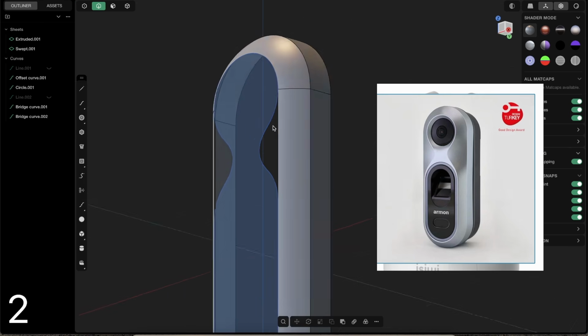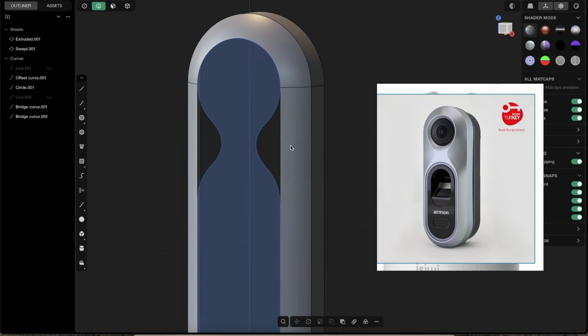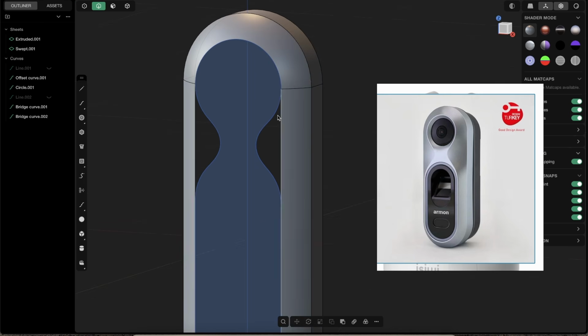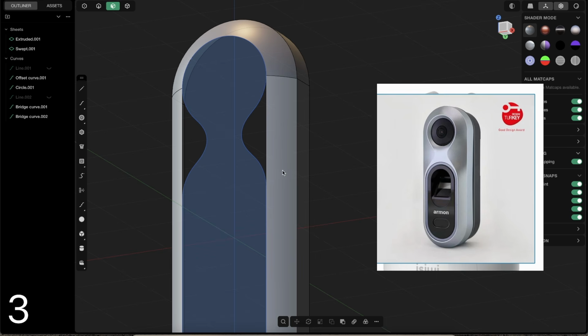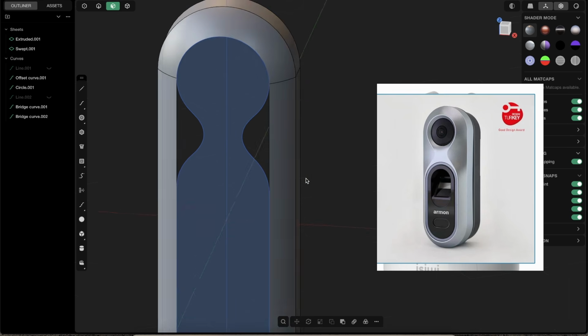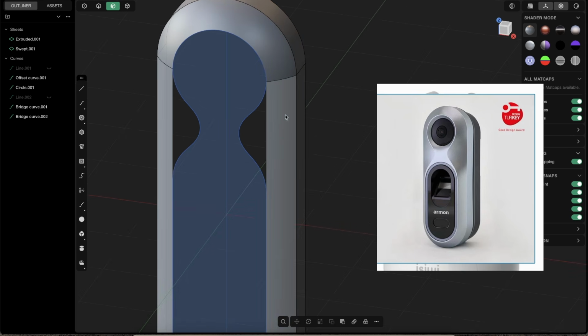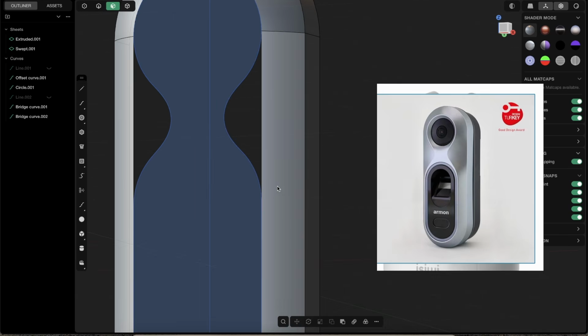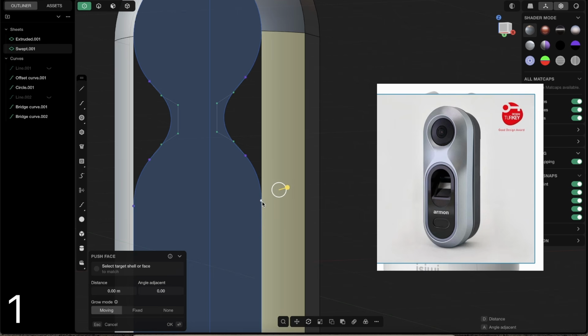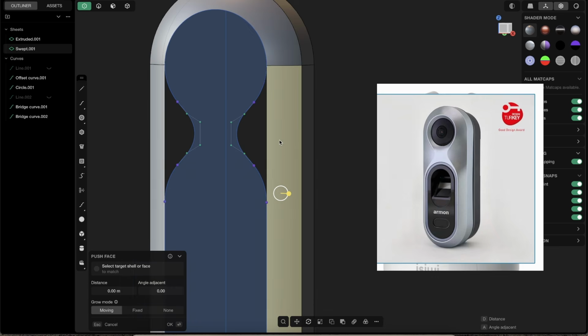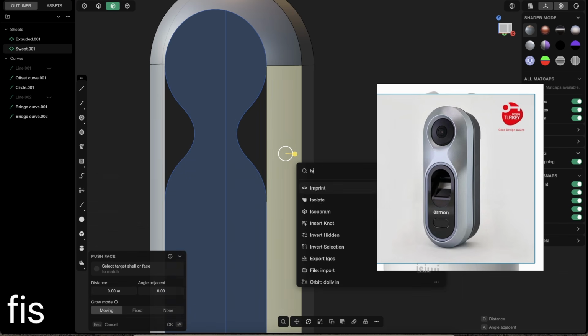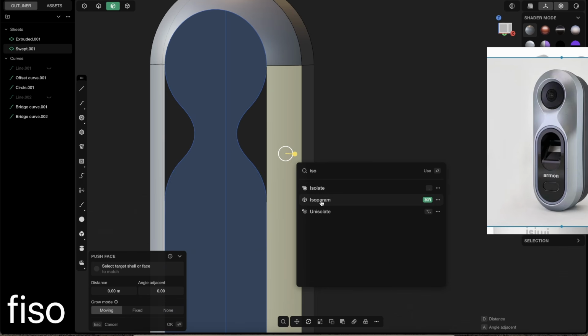And press 2, and now we have something very interesting, because now we have established here some place for this surface, but this surface is here a little bit in our way. So we want to cut this piece away. And where do we want to cut this piece? If you press 1, exactly where the circle starts again, right? So press 3, select this face here, and now important command, press F and isoparam this one.